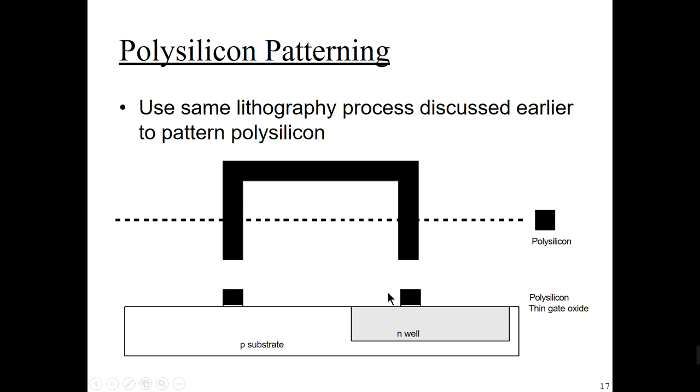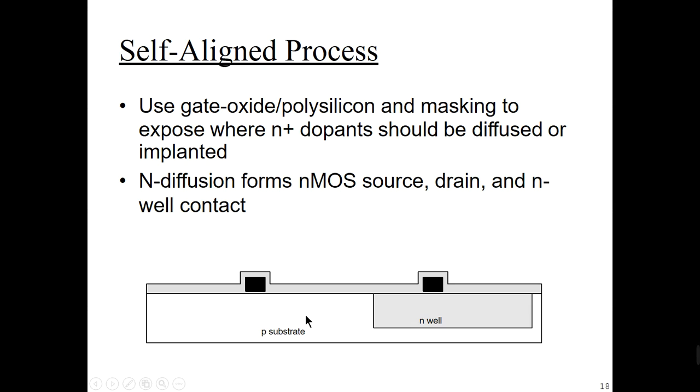And here in the N-well process we can place a PMOS transistor, and in the remaining second case we are using an NMOS transistor. After that, in the self-aligned process, the gate oxide, again some silicon dioxide material, is superimposed on the entire wafer.